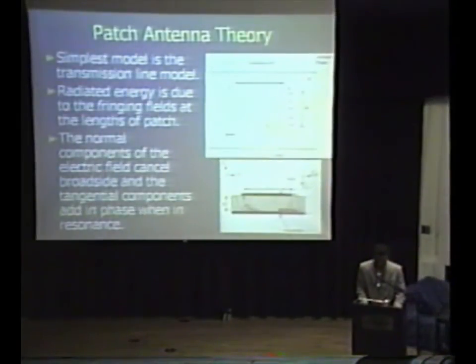Some of the theory behind the operation of the patch: the simplest model is the transmission line model. The radiated energy is due to the fringing fields at the edges of the patch, which are the curved lines on the bottom picture.